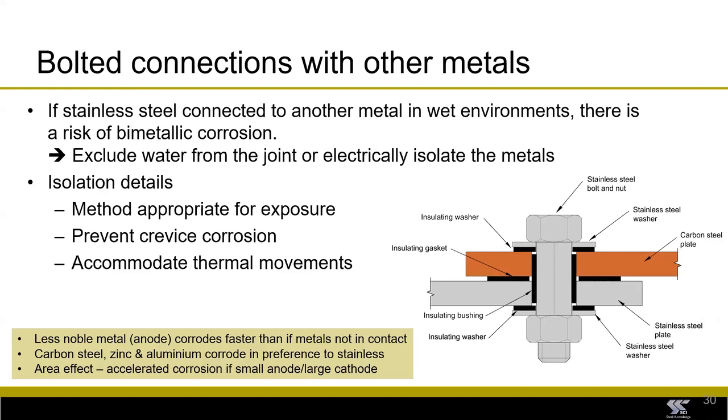Isolation tends to be materials like thermoset plastics, like neoprene, nylon, PTFE. This isn't new guidance. This has been used in the pipework industry for decades and decades, so these products exist.